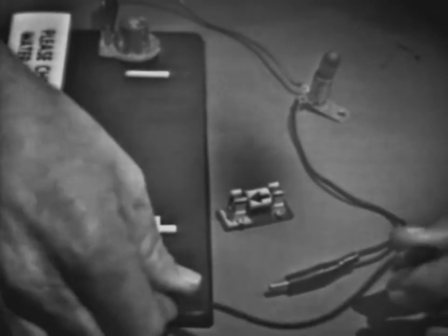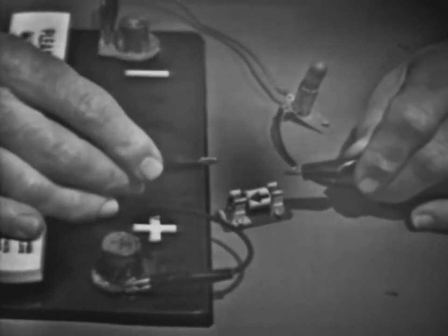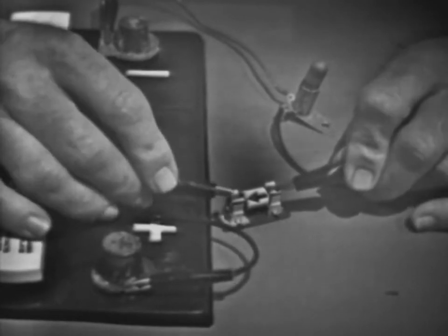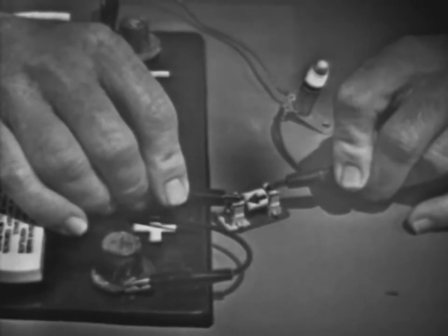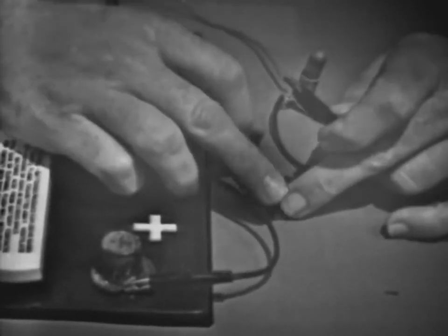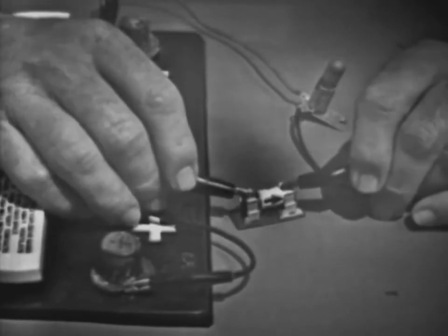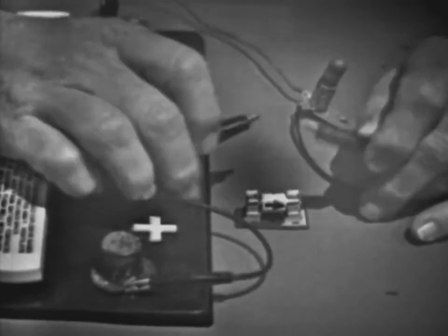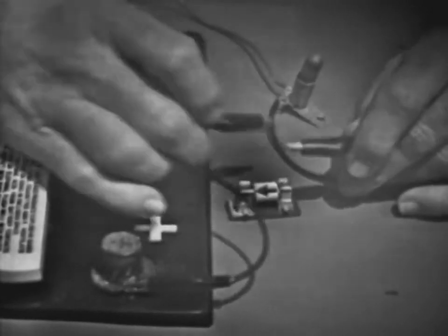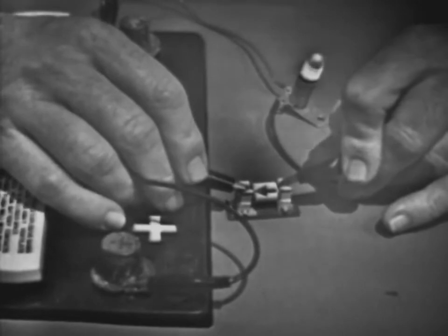This semiconductor diode is such a device. Now, I'll make a connection here. Move the bulb in so we can see all of the action. Now, if I apply current to the device in the proper direction, like this, the bulb lights. If I turn the diode around and try to make current flow in the wrong direction, nothing happens. So to make this diode work, we would have to know the direction of current flow.